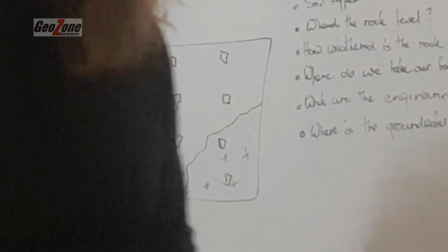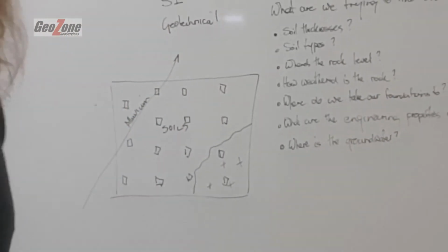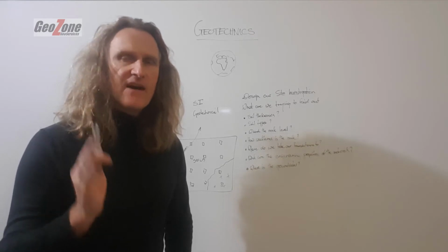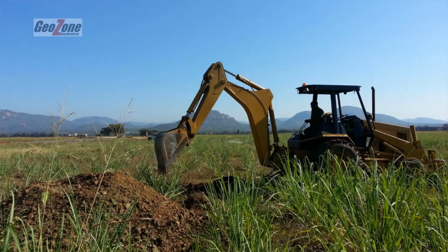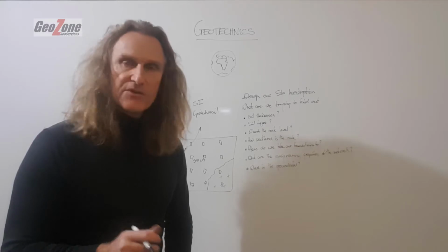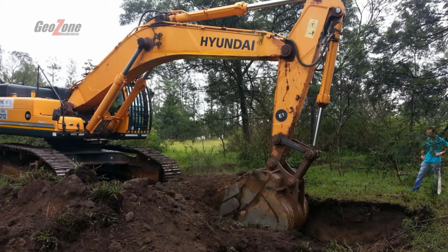We can do test pits. Test pits are fantastic in the sense that they are cheap, they're quick, and they tell you a vast amount of information. They give access to the soil profile, we can sample it, and if need be, we can install a piezometer in the pit. And so they really are very useful in terms of getting quick, good, and valuable data.